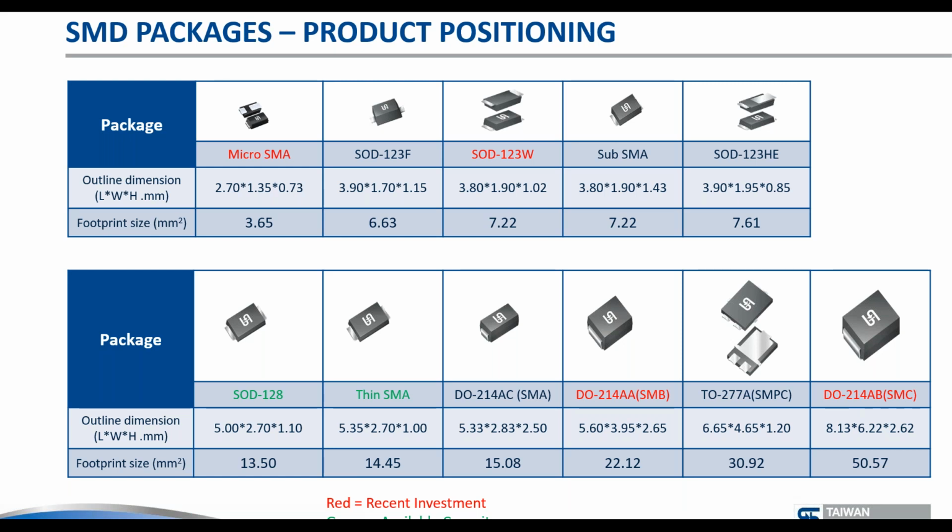I mean, obviously I'm saying the downsizing or automotive, because the distance between anode and cathode is 0.5 millimeters. So that means from a creepage and clearance perspective, the package needs to work in a low voltage environment. The package is actually very small and it has a copper clip. So this is really an excellent feature, that we can make packages now that are this small, that are clipped on the top and don't need wire bonding anymore. This is great for failure modes and all kinds of other things, thermal things. So excellent package here, great future here.